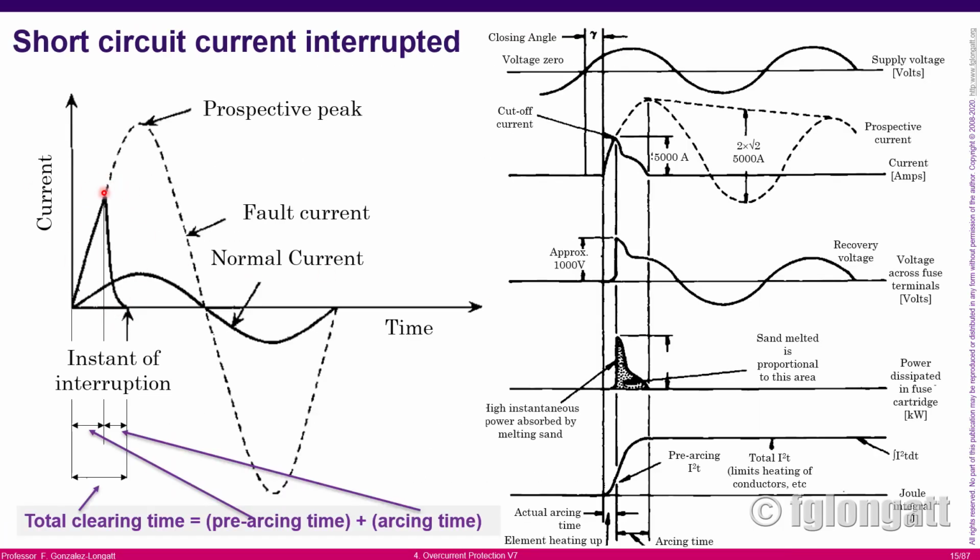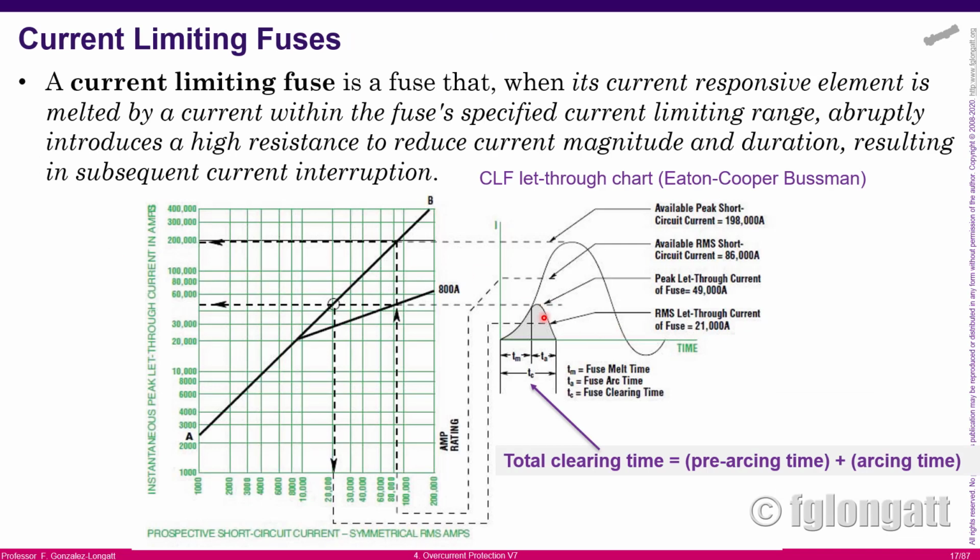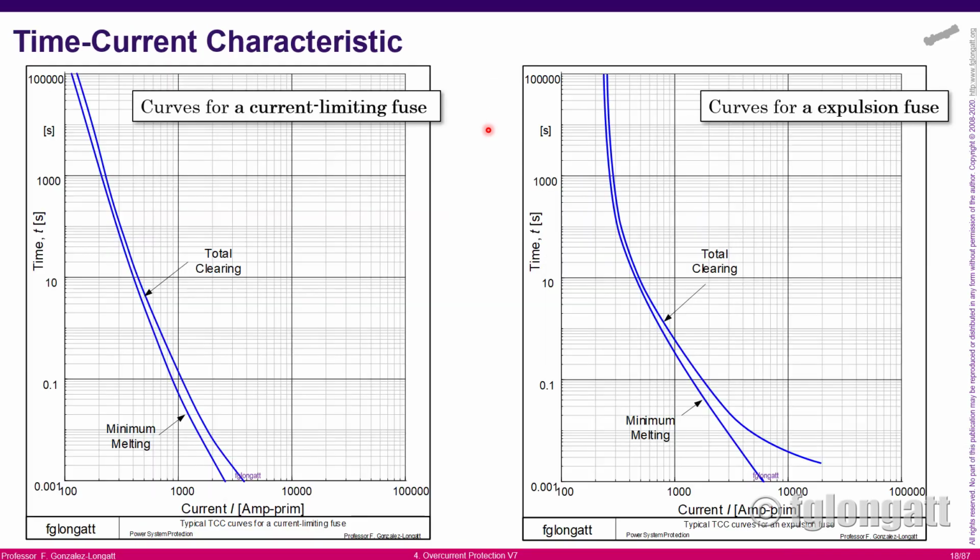I believe here you can see a sudden, very fast drop in the current, but here it is quite smooth, and to be honest, it's almost linear or something similar to that. And it's mainly because of this limiting range, where the fuse has the possibility to introduce this resistance, limiting the current that is moving across the terminals, okay?